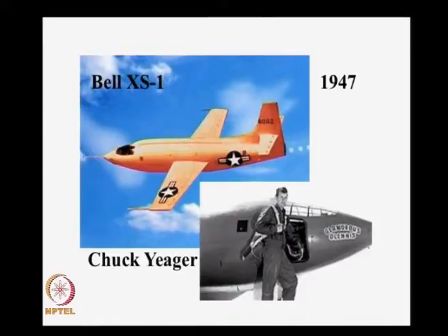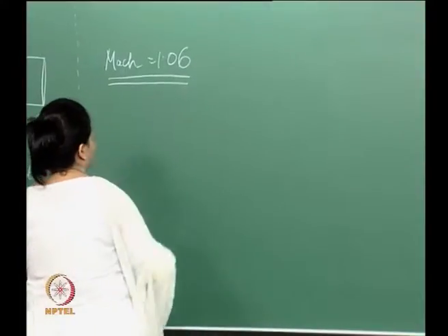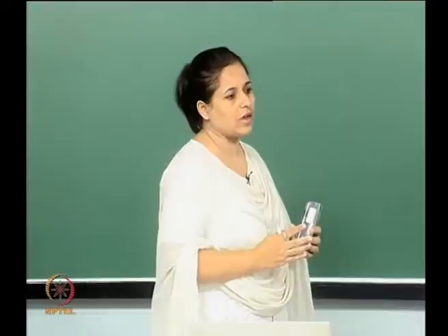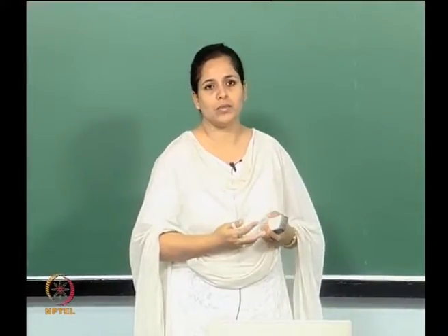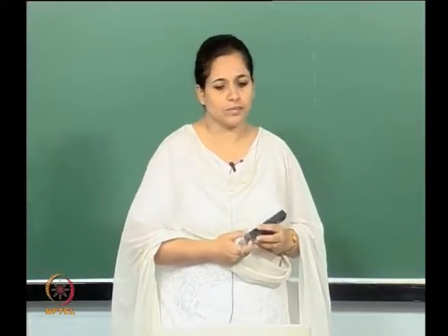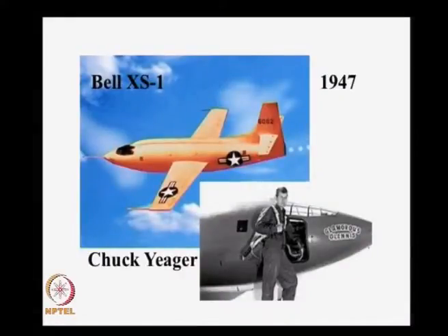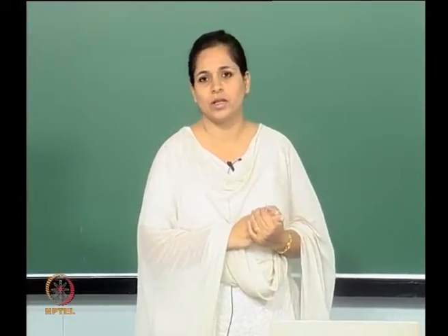Well, the reason is that the thrust in the Bell XS-1, the thrust in this plane, was provided by 4 convergent divergent nozzles, and that was what was able to move the Bell XS-1 at speeds for which he was able to reach Mach 1. So essentially, from a very simple experiment which Laval, a Swedish engineer, used on a rotator wheel, he used the principles of compressible flow, and we've been able to catapult that and use it for something as sophisticated as supersonic flow.